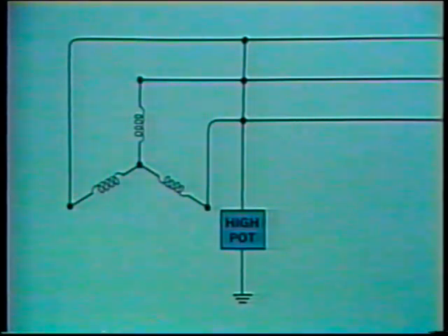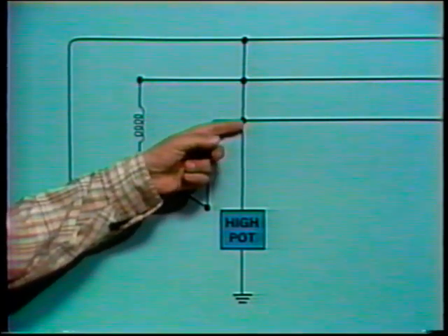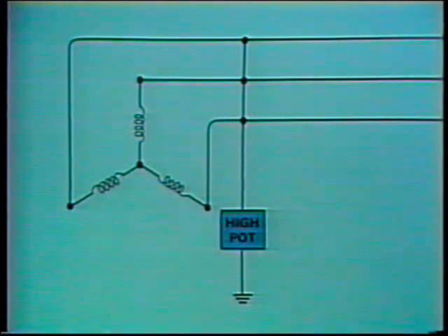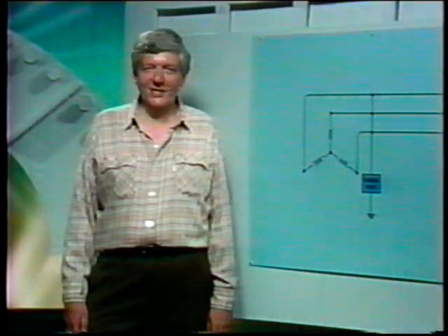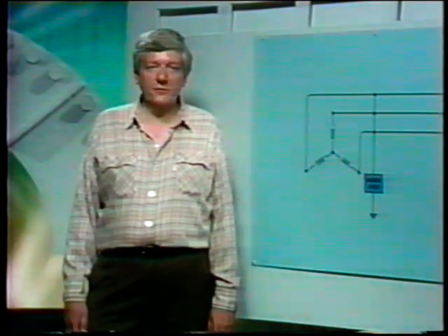The high pot test setup is very similar to the megometer setup. First, the generator is isolated electrically, and its output terminals are tied together. Then the high pot tester is connected to the terminals and used to apply the test voltage. Generally, the test voltage is maintained for 1 minute, but the length of time may vary. The length of the high pot test in your plant will be determined by plant or company policy. If the insulation withstands the test voltage, it passes the test. Following the test, the generator must be discharged to remove the test voltage.